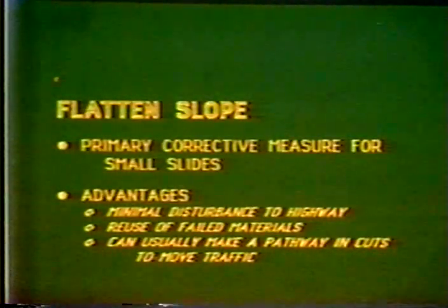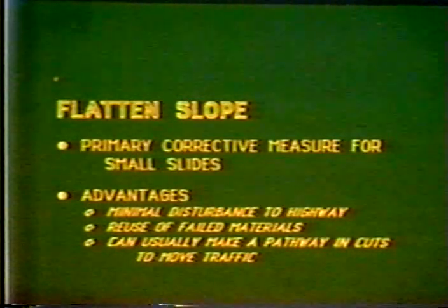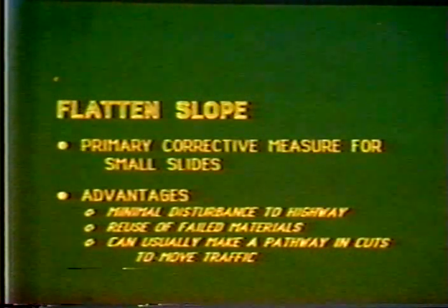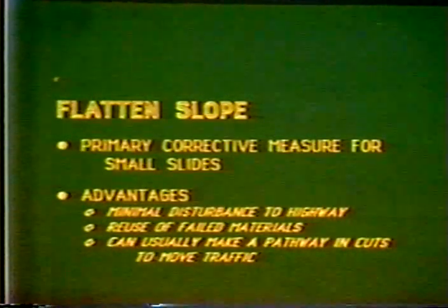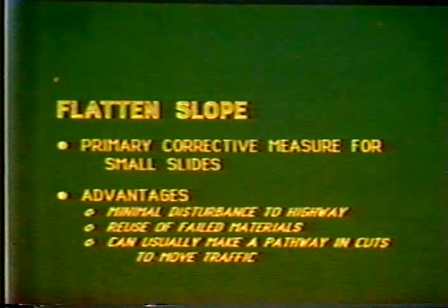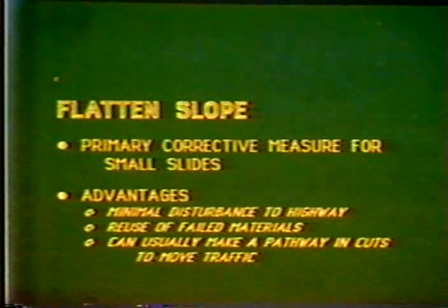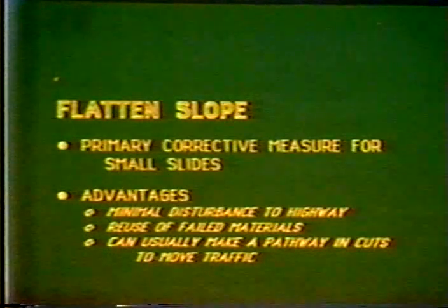First, I'd like to say that flattening the slope, and I like to emphasize this, is a primary corrective measure for small slides as well as large slides. There's certain distinctive advantages when we use this technique. One that we call minimum disturbance to the highway. In other words,